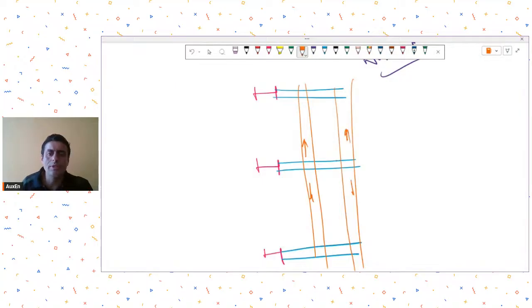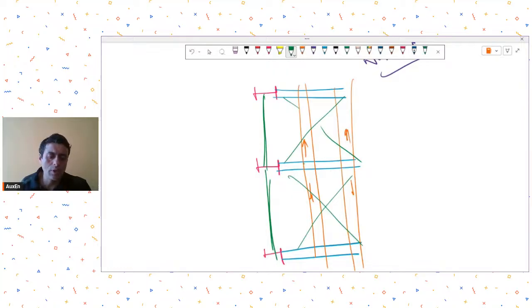So what you can do in such cases is you can try to connect these elements together. Maybe think of providing some bracing between these beams to take care of the torsional forces that may get generated on this blue colored beam. So to take care of the longitudinal forces along the length of this pipe, you provide some bracings in between these cantilever members as shown. This is the plan view.